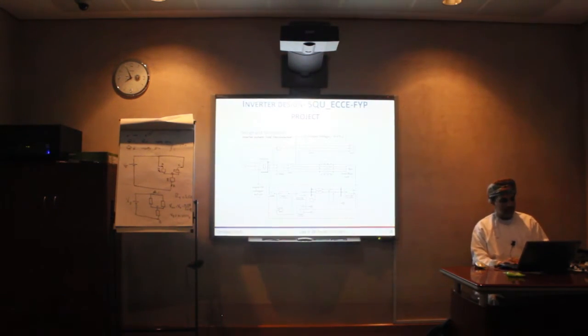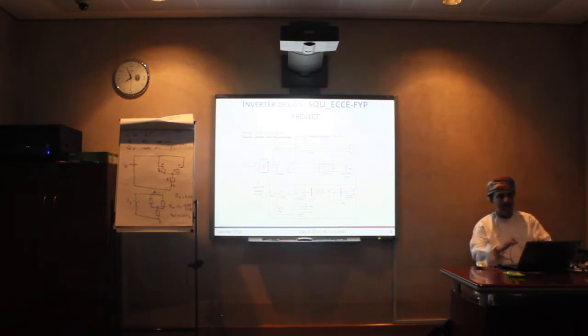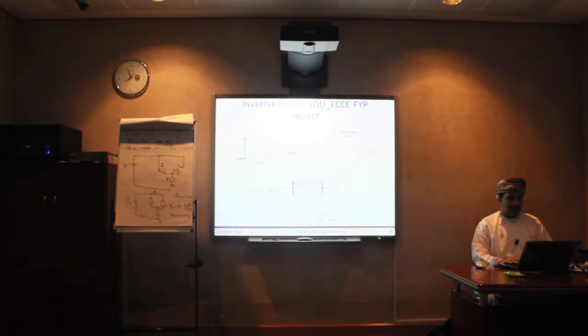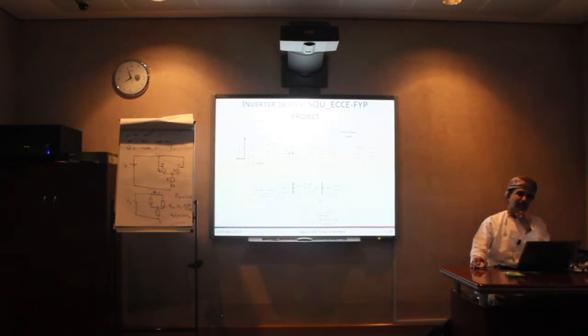This is the simulation. They simulated the inverter as an isolated system. They added a control loop. I am happy to explain this control loop to you later if you want. I don't mind, you can come to my office and I will explain everything here. And they also connected it to the grid. They did this one with VF control, voltage and frequency control. And that one they made with P and Q control, and they actually operated this inverter at unity power factor.